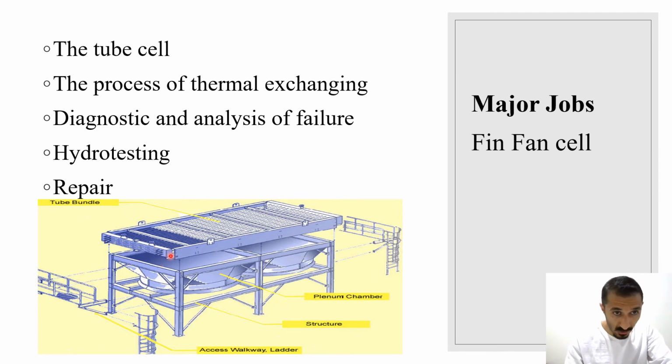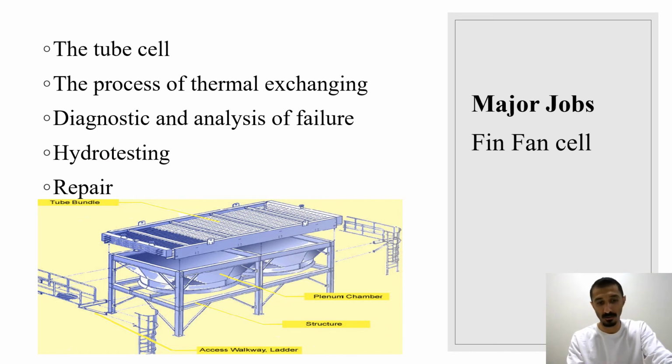As you can see here, the tube ends of each tube inside the tube bundle, and here we have the other end of the tube. Here we have the inlet, here the outlet. I do one by one. I find the broken tube, I plug it from both sides using specific tools, and this is where I do my repair.